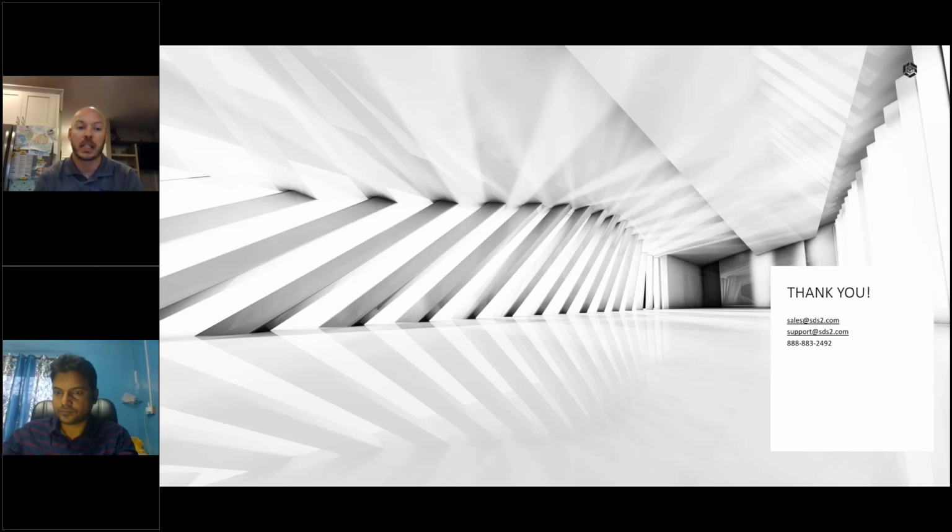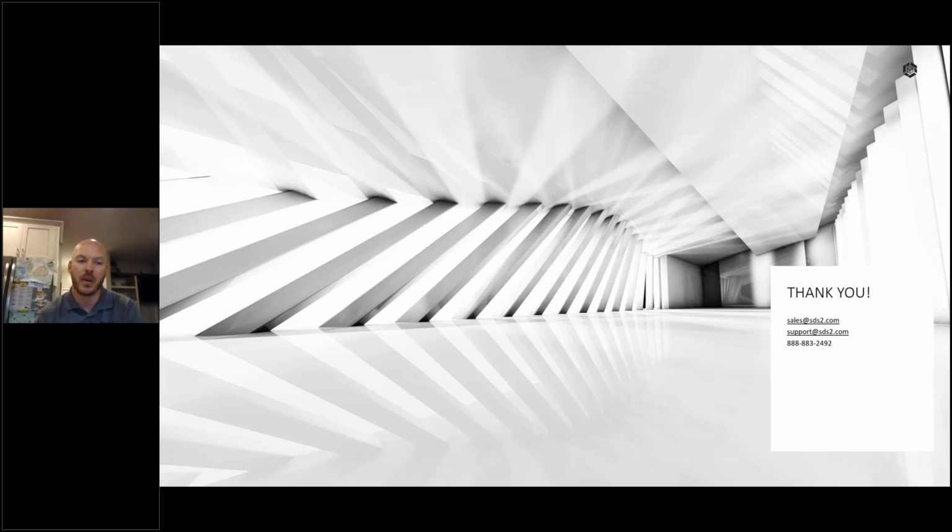Now, SDS2 does track what is out of date. So we flag that with a flag that we call marked for detailing. So when the model changes and now that means the drawing is out of date, there is a flag marked for detailing on that member that indicates to us that it isn't up to date.